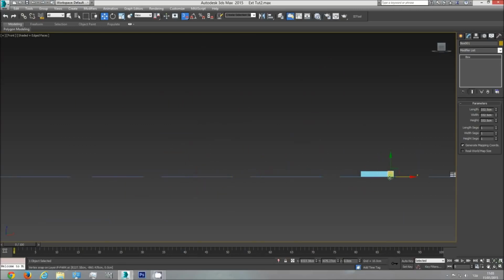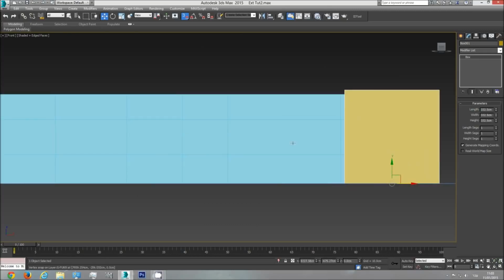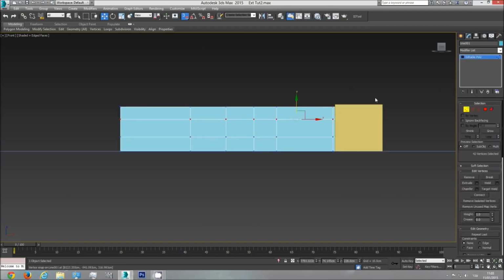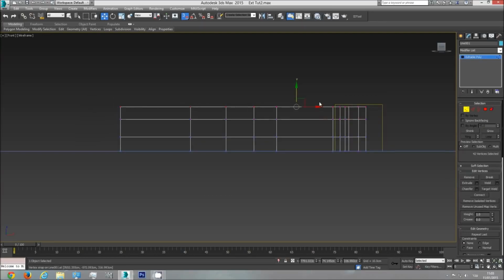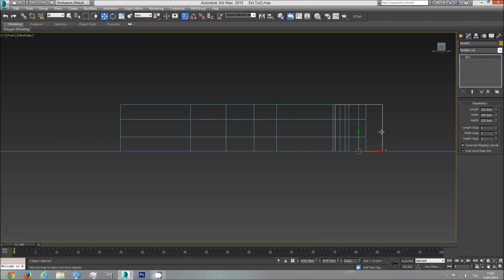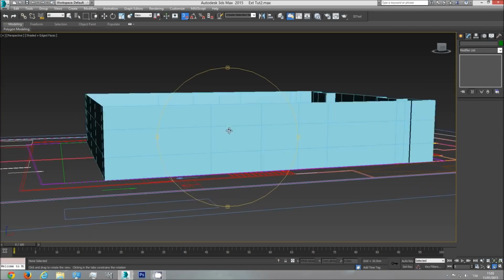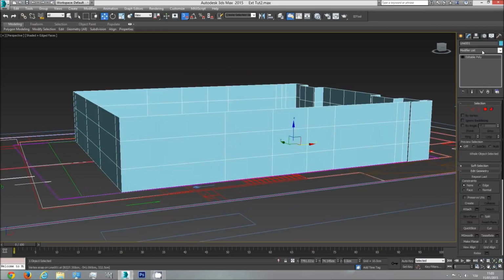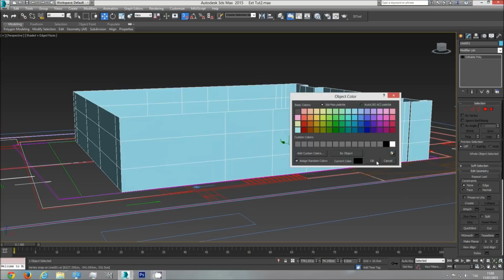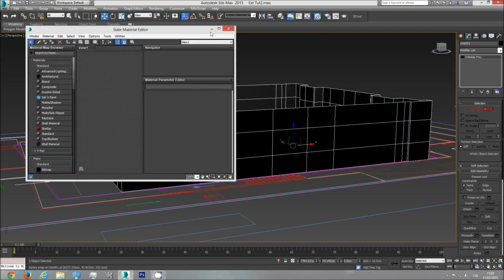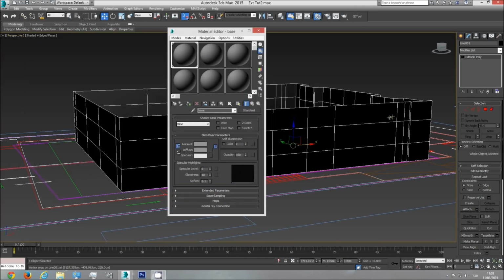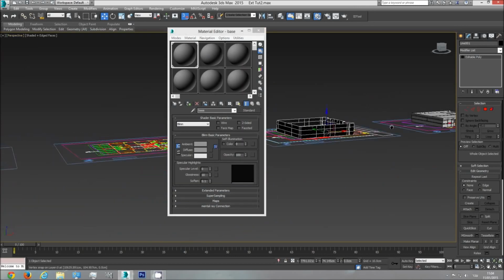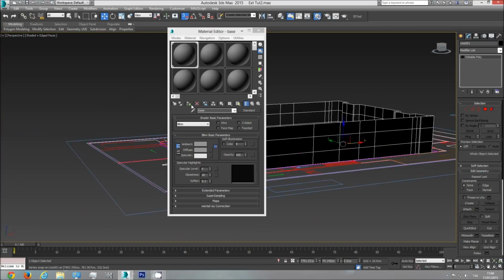I'm going to take it here. It's in 0. And now I know that our ceiling vertices go here. That's fine. Okay, so now I have a first floor. I have the bottom height, let's give it a black outline color, and, sorry, let's change the mode to compound material mode, and the same material as this basement level. So I'm going to give it base material.